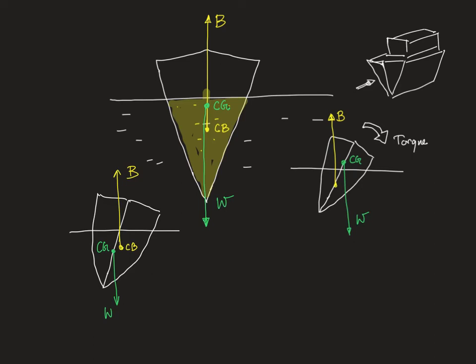Got this point? This center of buoyancy, see, it is the center of gravity of the displaced part of the fluid. So the main thing is the torque should be a restoring one, which will try to restore the ship to the equilibrium position.